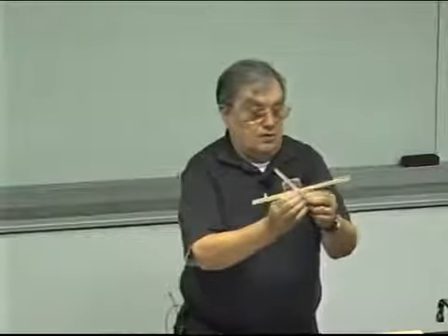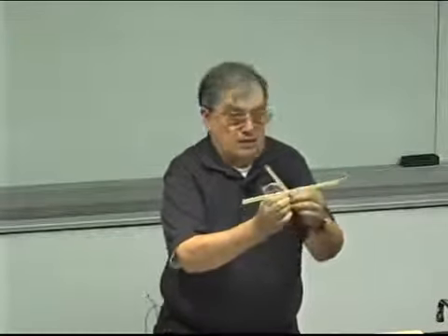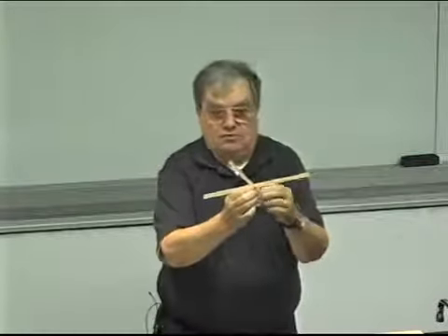You're going to want to cut the wood. Depending on what kind of joint you want to make on the wood, depends on how you want to cut it. There are two types. If you want to make a lap joint, this is a lap joint. Let me use these two pieces here. Those two pieces cross over each other. It doesn't make any difference how you cut the end. Okay, if they're going over like this, you can just kind of cut the end however you want.